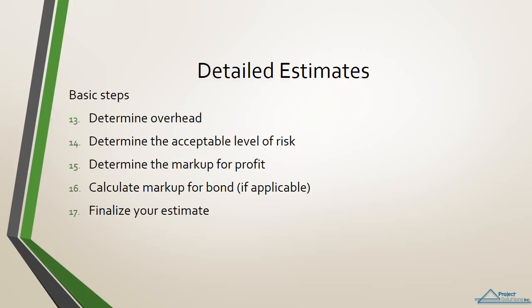Number 13, determine overhead. Number 14, determine the acceptable level of risk. Number 15, determine the markup for profit. Number 16, calculate markup for bond if applicable. And number 17, finalize your estimate.